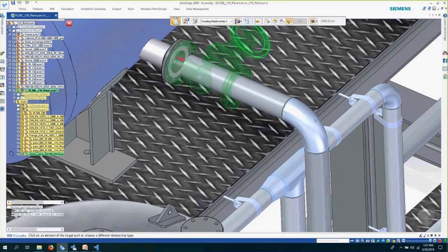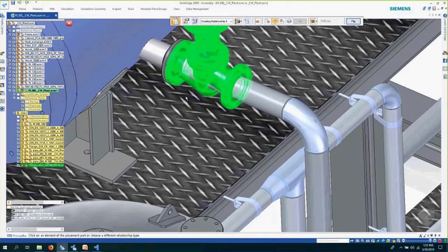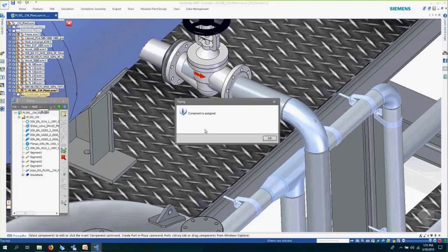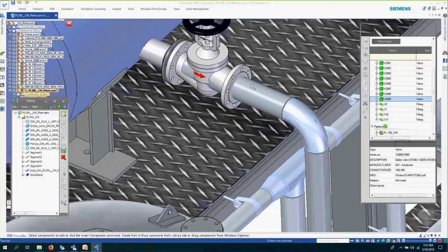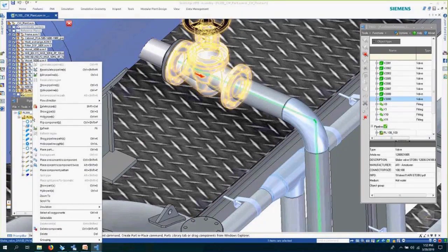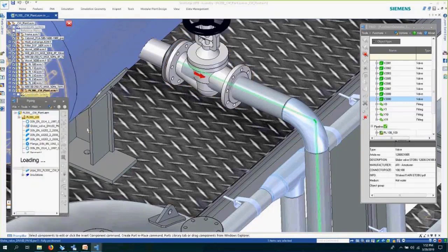And so we can actually have all of our capture fit information already added in here. Again, just base Solid Edge functionality of building my assemblies. So I get it placed into here. Life is good. And then I can tell it, all right, let's update all of the pipes and make sure that there's no finished connecting information that might be missing here. So we can recalculate this pipeline.